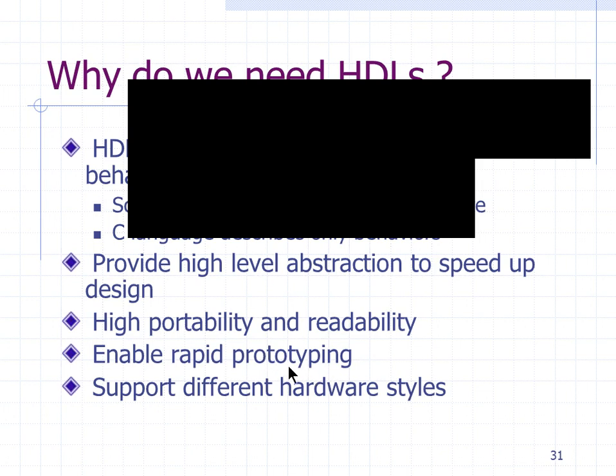That's prototyping. It also supports different hardware styles. We have seen structural style, we have seen behavioral style, and we will also see some special methods. Verilog as a language can support these things, where with schematics it was difficult. Those are some of the reasons why we need HDL languages compared to schematics.